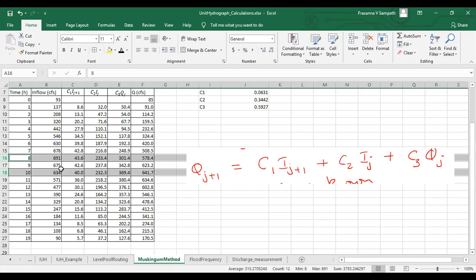So you accomplished two things. One, you managed to reduce the peak. If the peak is reduced, then the area that will get flooded will be reduced, so the impact is lower, and you also get more time for planning and so on. Is that okay? Any questions on this? This is the simplest possible way of looking at hydrologic flood routing in a channel.